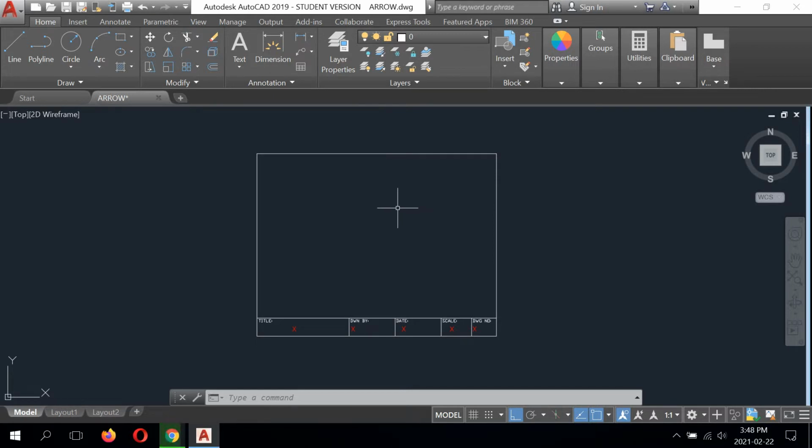So what I'm going to be doing is finding the middle first. So if I flash my cursor over this line and this line, it highlights, right? It's showing that when I touch it, the line is active from the very top to the start of the title block information. So what I'm going to be doing is drawing a line, picking up the midpoint snap. So I grab line, come over here, find the midpoint snap, left click, and come down and left click the midpoint here.